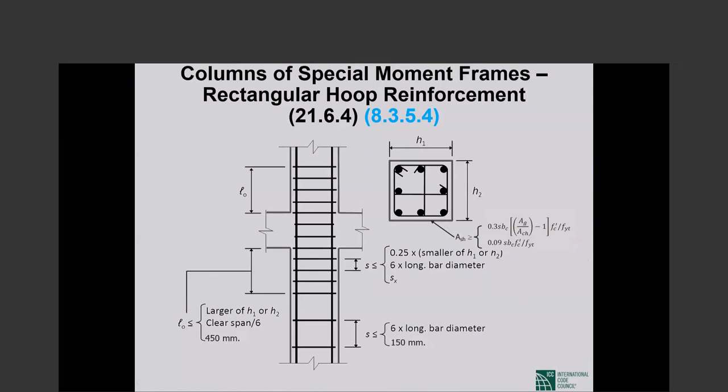When you figure out the shear reinforcement required, we discussed the shear design module of the concrete courses. There you use the yield strength of the shear reinforcement, and there you will not go beyond 60 ksi. That's all. There is no contradiction.